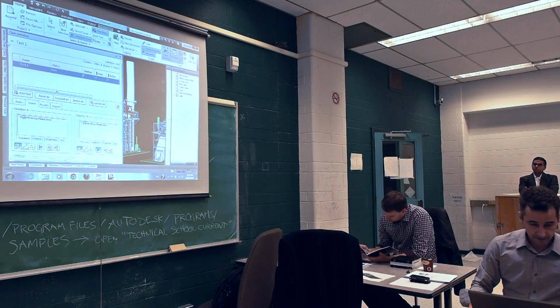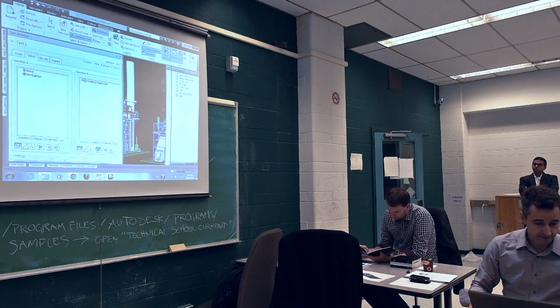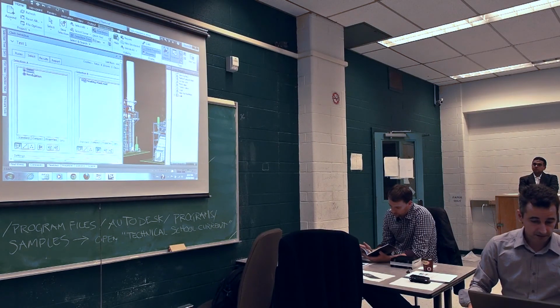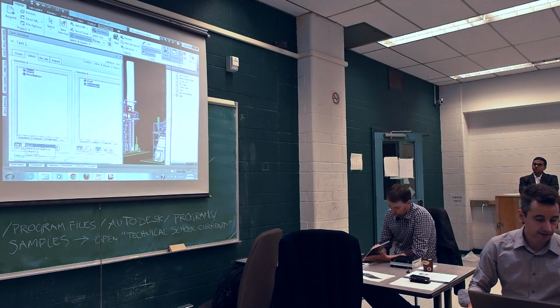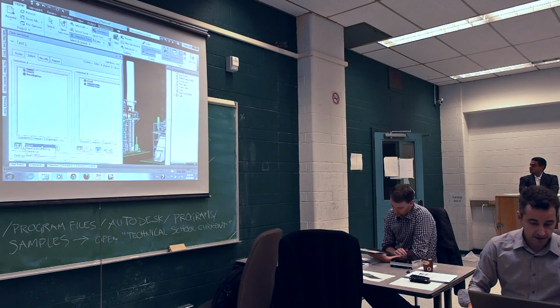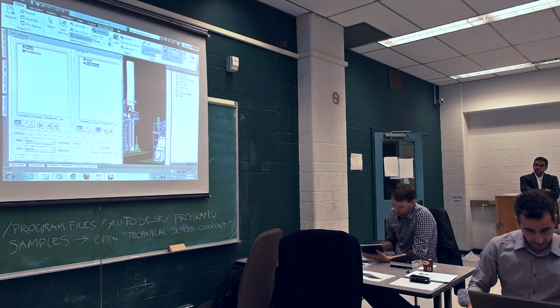And in my selection panes, I go to selection sets, that means. And I'm going to do steel versus ventilation. I have to be careful to uncheck the self-intersect. And somewhere in here, I have to define the clash type. I'm going to do hard detection, hard collision, and the tolerance is going to be 4 millimeters. And I'm going to run the test.